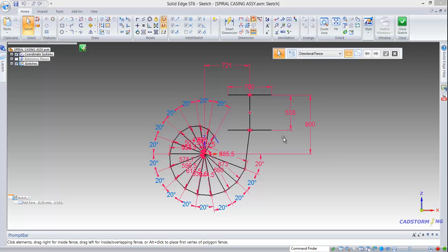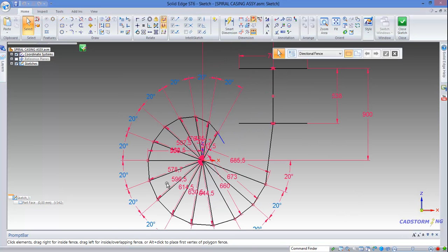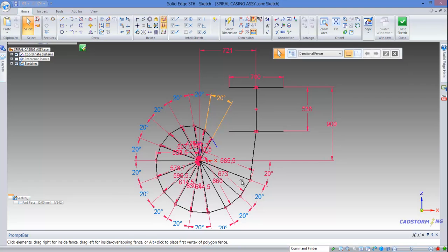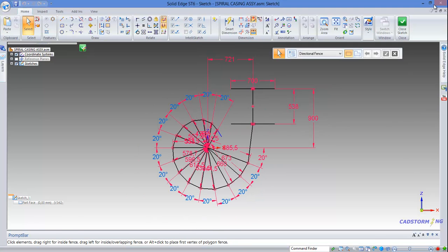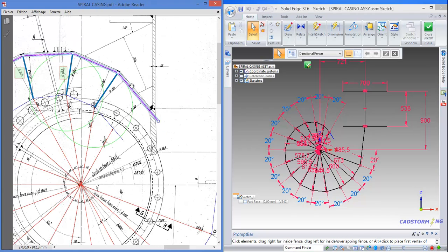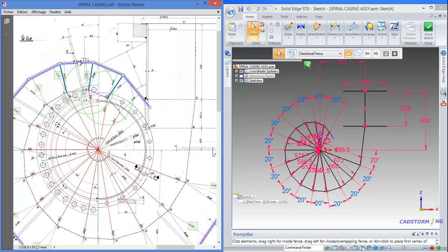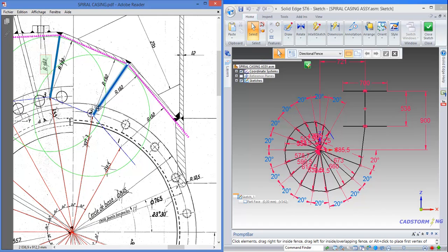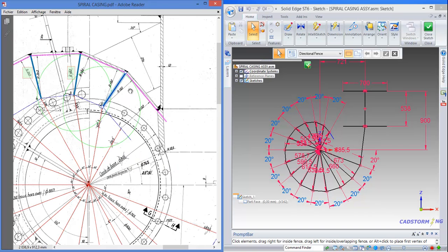In part 1, we start to build our master sketch. We managed to create and properly constrain these radial lines and then create the center line. The goal of this part is to create these guidelines for our future roll sheet metal components, and from them we will define the location of the profile sketches. Basically, there will be planes normal to the screen and passing through these lines.